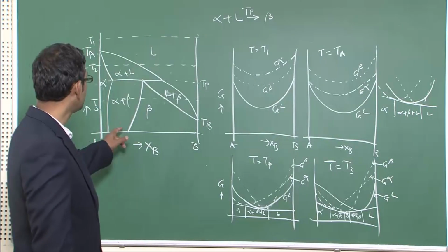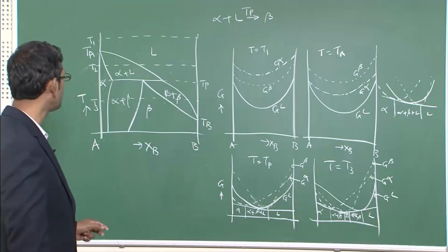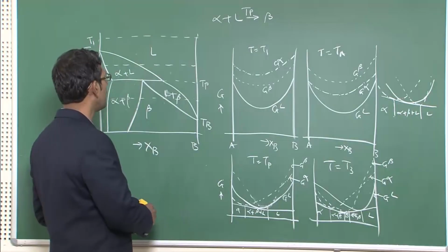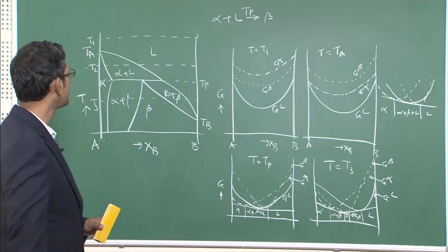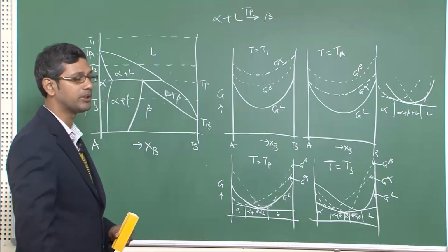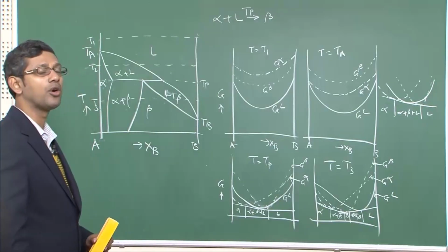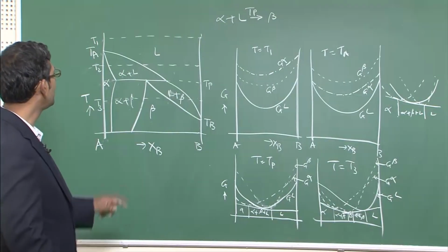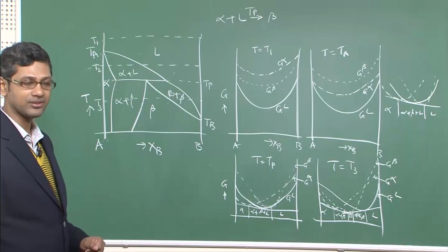Now beta here is a solution phase between two components A and B, but it can also be an intermetallic phase, or it can also be a line compound, just like a line. I have shown you in the iron germanium phase diagram. There are many compounds like FeGe, Fe5Ge6 like that. So these phases are also formed by peritectic reactions.